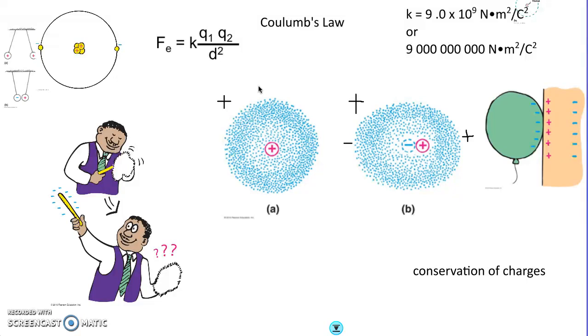Now, static electricity can still be a problem. People working on circuits and transistors and small chips and various things have to be very careful. They try to wear outfits that have low static electricity. They may have little ground wires going from their cuffs down to the ground to leak off any charge that builds up, because the smaller the chip, the smaller the circuit, the amount of electricity that goes into it to begin with, the static electricity could cause damage and destroy those circuits. So it still can be very important, but it's not what we think of for turning on light bulbs in our home or keeping a city in electricity.